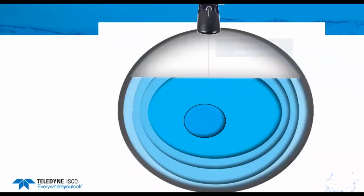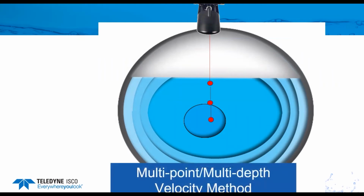All right, so what does this thing do that's a little bit different? It uses an ultrasonic, just like the other one, to measure it. In this case, due to the power requirements and restrictions we had, we can only do the 3 points in the middle. So we were a little bit limited on what we were able to do, but for the most part, all the testing we've done, as long as your hydraulics are reasonably good, this method works quite well.